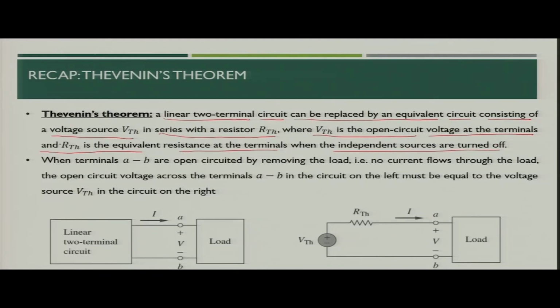When we calculate Rth, the independent voltage source is short circuited and the independent current source is open circuited.